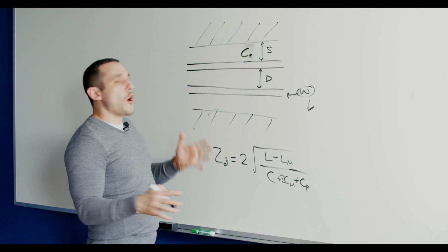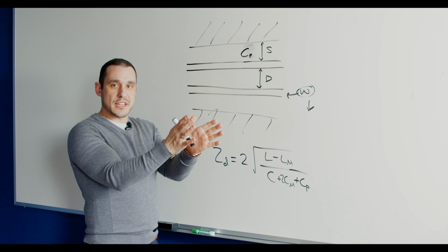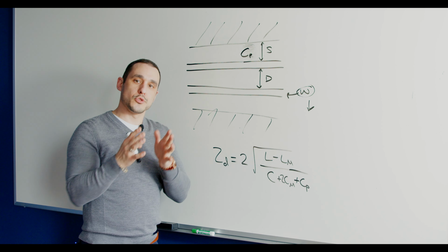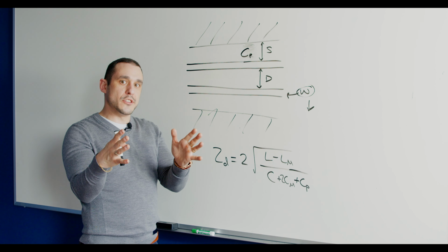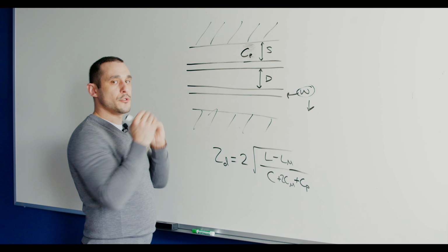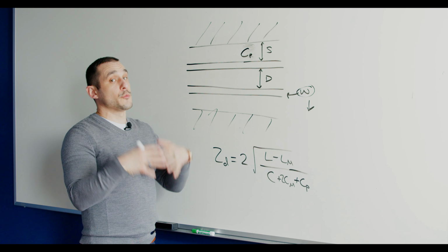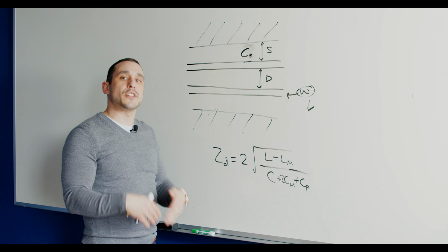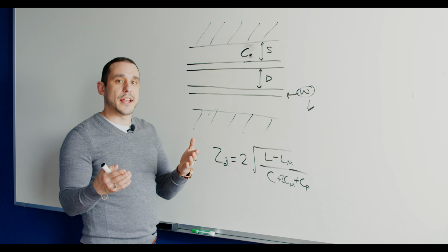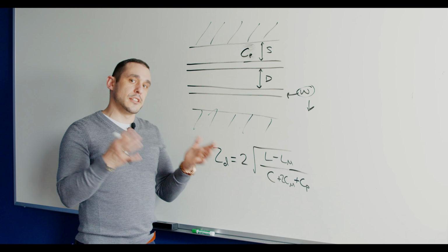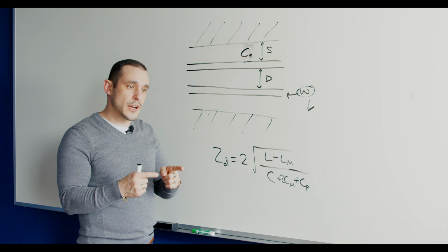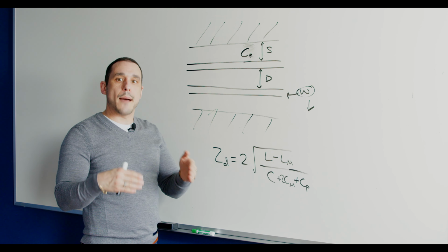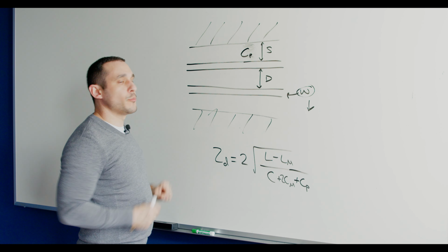So again, if all you did was take a single-ended transmission line or a differential transmission line, and then as it sits, bring copper pour in too close, you're going to start to reduce the impedance of that line. And if you reduce it too much, you could then create too much return loss on that line. So to examine this a little bit deeper, let's hop into Altium Designer and hop into Polar, and let's take a deeper look at what happens when we add in grounded coplanar copper pour.